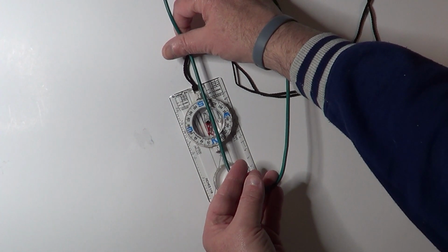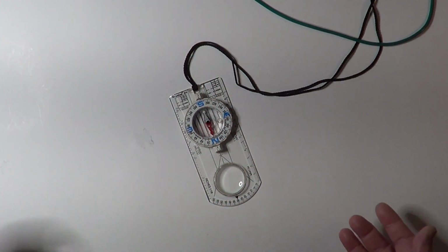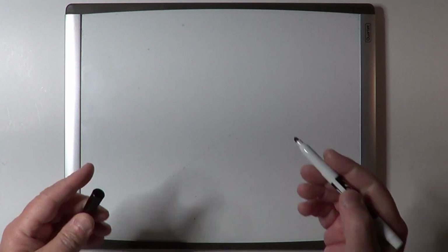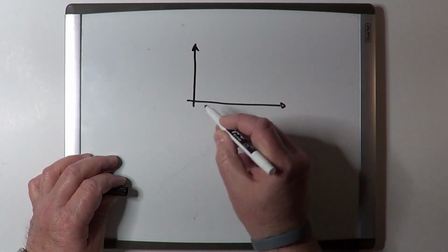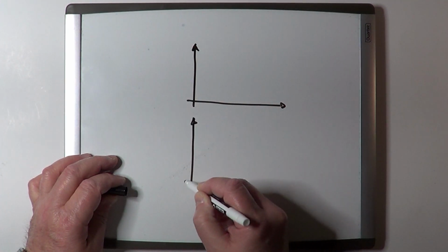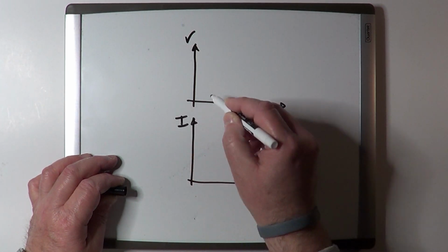Can you see it? So this basically demonstrates that current generates a magnetic field. So back to the original question, the current does not change instantaneously when the voltage changes on the wire, because the voltage has to provide first enough energy to modify the magnetic field. Only when the magnetic field is modified, the current can change. So basically that explains why we see this kind of behavior between the voltage applied on the inductor and the current that flows through it.